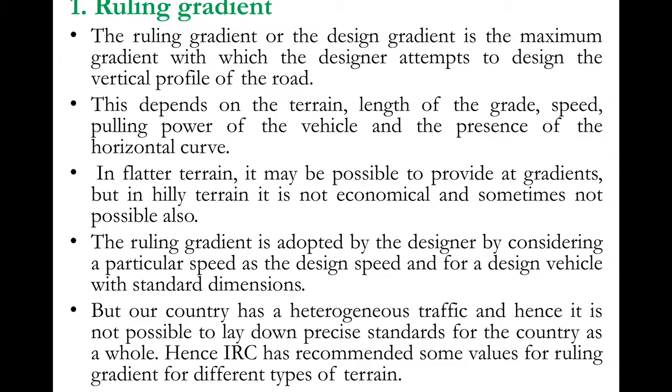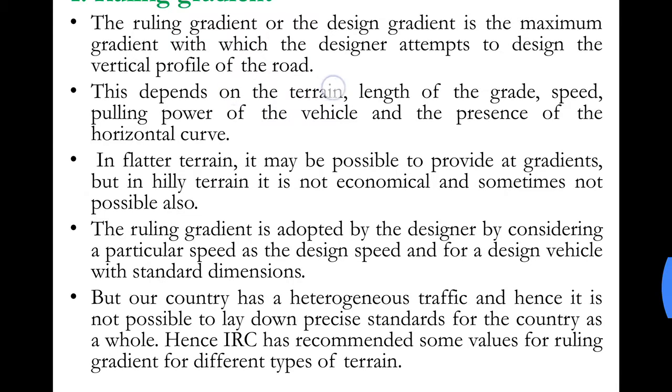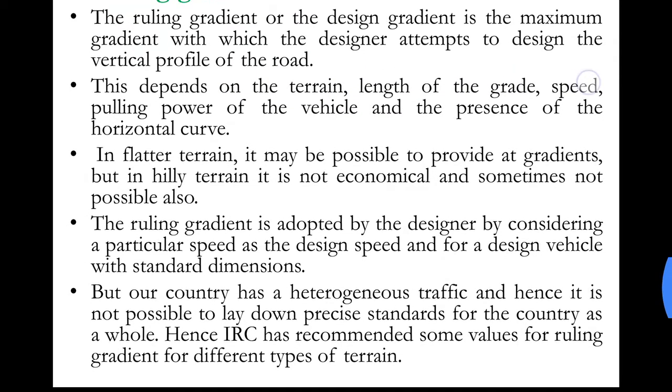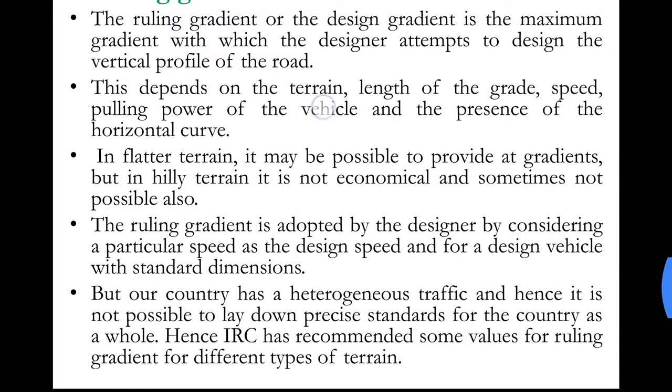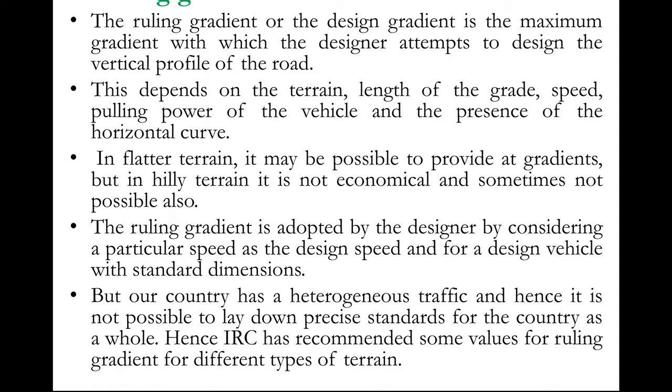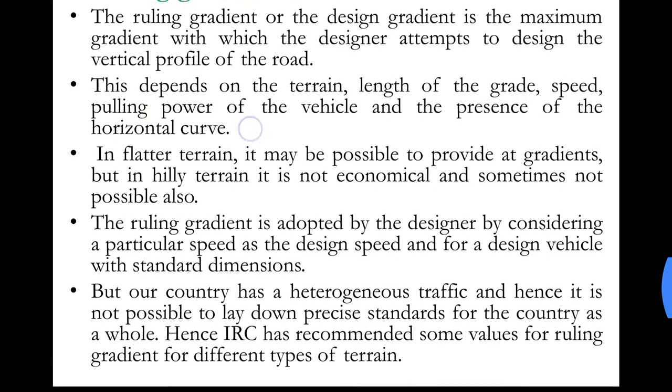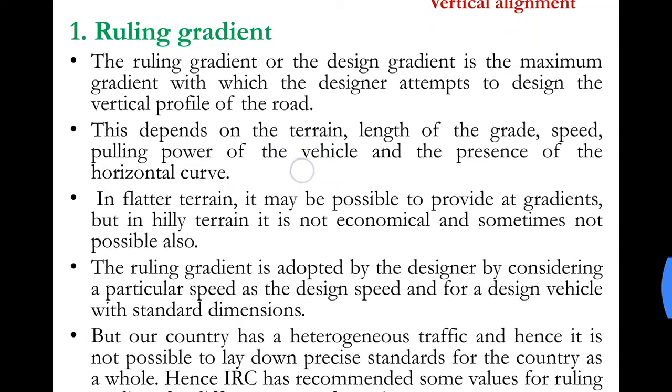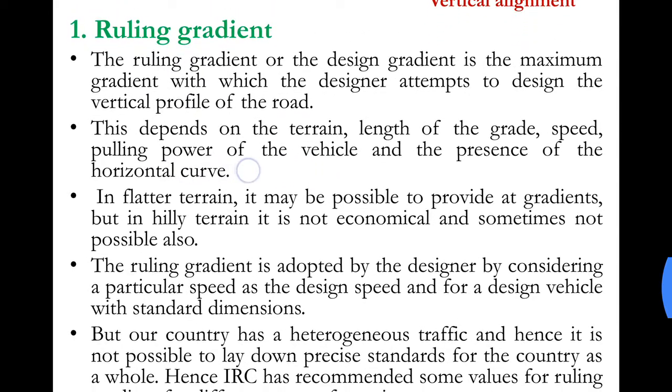It is the gradient value that is used in order for the road design. This depends on the terrain, length of grade, speed, pulling power of the vehicle, and the presence of the horizontal curve. So in the presence of horizontal curves, we will not be able to provide steeper gradients. We will have to provide gentler gradients.